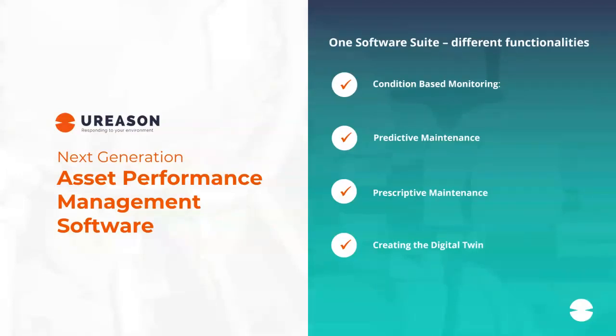Another question: is high frequency data needed to train machine learning models? Not really. It depends on the type of failure that you would like to predict. If you're looking at shaft alignment, for example, or wear and tear of bearings, in those cases we need high frequency data to train models, and also access if you want to put those online on the streaming data source, either via OPC or another method, to have access to the vibration data.